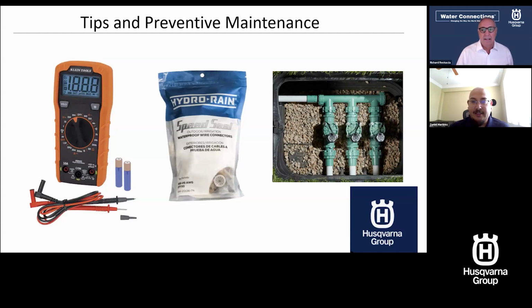If you look at that little window on the bag, they have a silicone sealant in there. So even if your valve box fills up with water, your wire connection is still protected and it's not going to ground to earth. And very lastly, keep those valve boxes nice and clean, easier to work on, easier to test in the future.